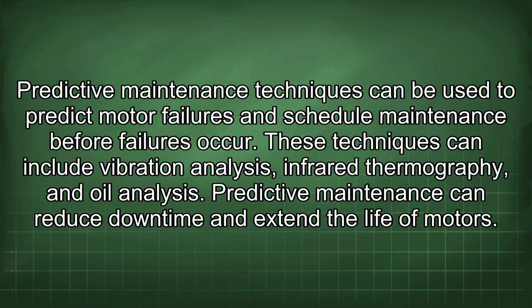Predictive maintenance techniques can be used to predict motor failures and schedule maintenance before failures occur. These techniques can include vibration analysis, infrared thermography, and oil analysis. Predictive maintenance can reduce downtime and extend the life of motors.